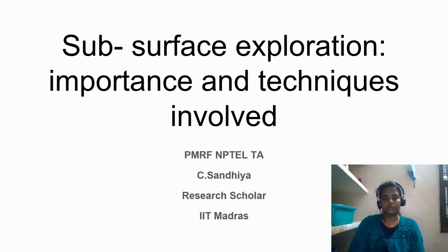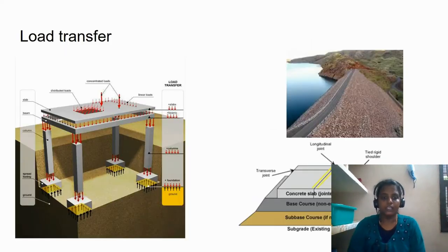Okay, subsurface exploration. Why do we need to study this course, and what is the importance of it? I'll just have a small intro. Any structure that is going to be built on this earth is going to transfer the load ultimately to the soil. The soil is the one which is going to carry the load from the superstructure, transferred from the slab to beam, beam to column, column to foundation, and finally to the soil.